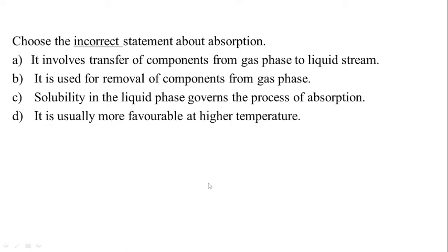Now, in such cases, sometimes you will find, I had mentioned in one of my earlier interactions with you a column top pressure control using a hot bypass line. A hot bypass line basically will be controlling the submergence.